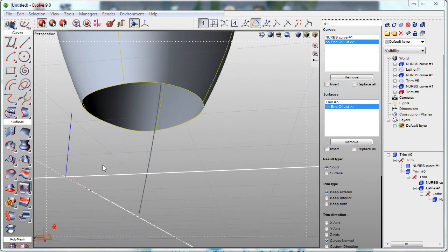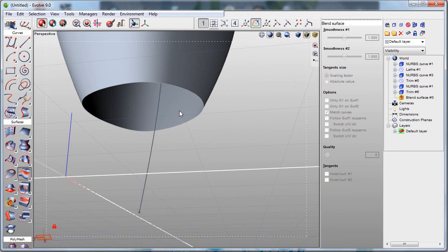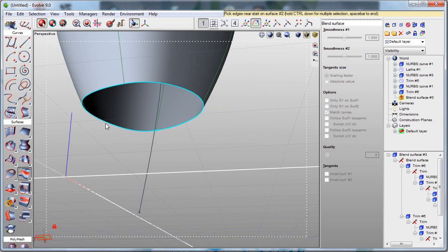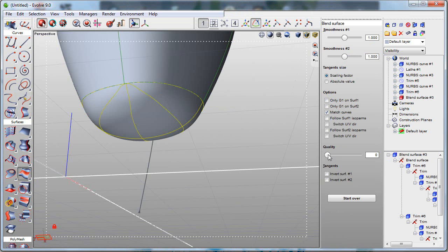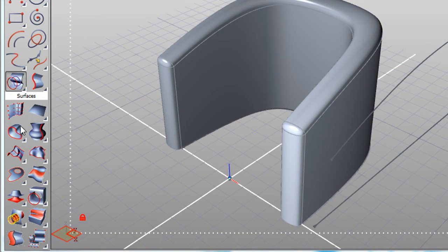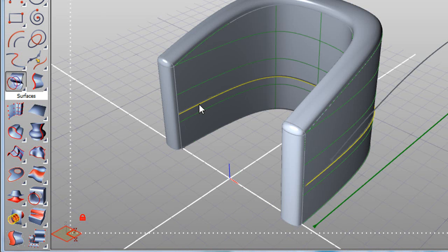The software also has an automatic surface patching tool. It's a very useful way to connect surfaces that are apart from each other. There is also the option to project a curve from the outer plane onto a surface that is away from it, called path casting. I'm using the command, for instance, to create the surface that I will eventually use to create the cushion for this seat.